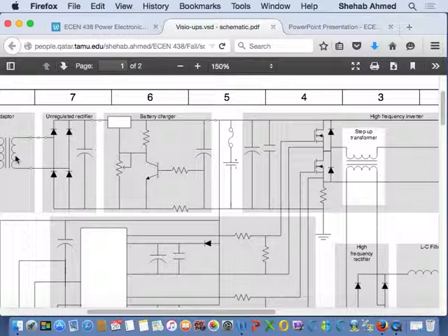So if you charge a battery with 5 amps, that's called C rating. If you charge it with C/2 rating, that's 2.5 amps. If you charge it with C/5 rating, it's 1 amp. So you're putting in 1 amp for 5 hours, right? So batteries like to be charged in a certain fashion.